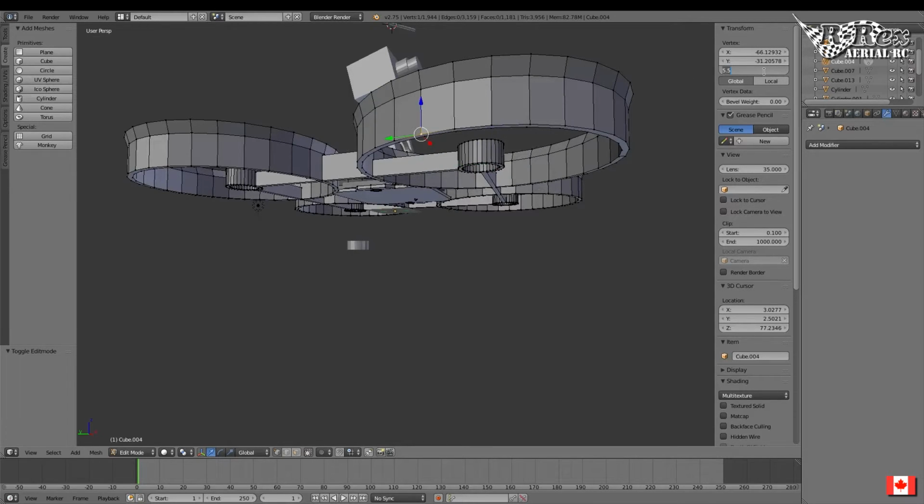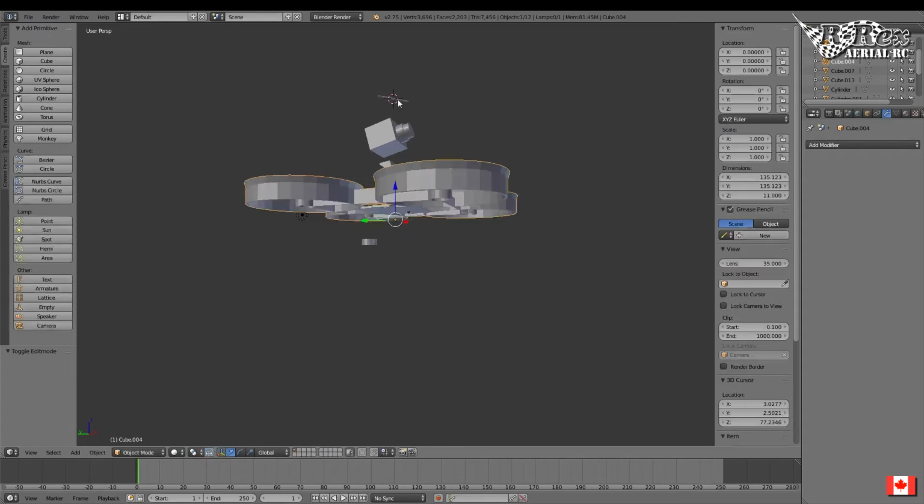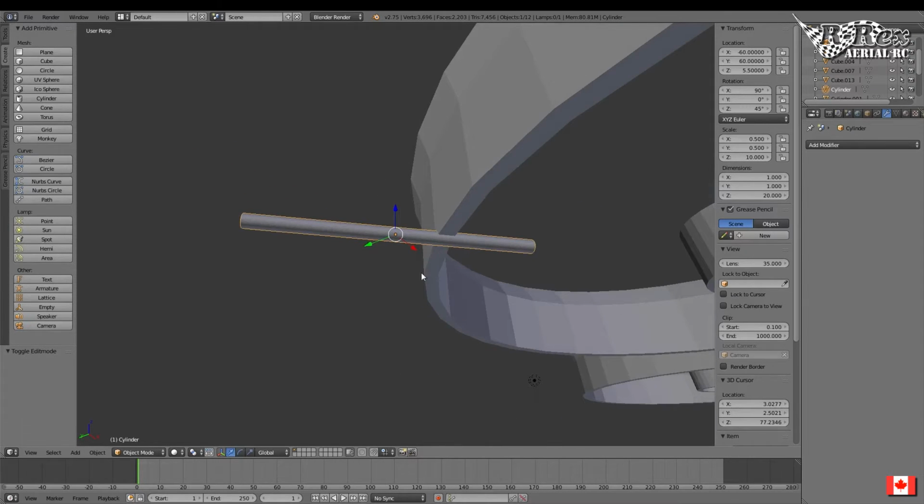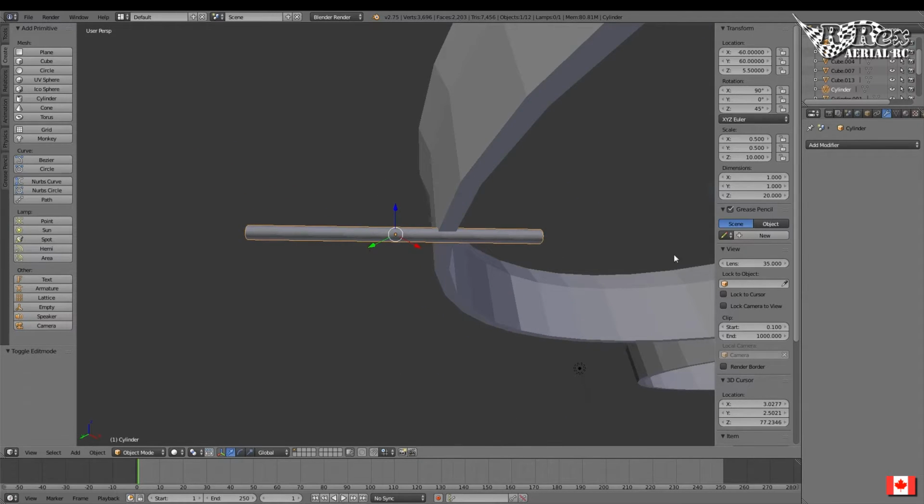So I'm going to line this up at 5.5, and set it to, let's try 60 by 60. Nope. Negative 60 by 60. There we go. Now you'll notice that it just slices through the edge. Because this is 1 millimeter thick, it slices through 0.5 millimeters, which means the first layer, and if you do a 0.1 layer, the first layer and the second layer will be detected as lower surface.